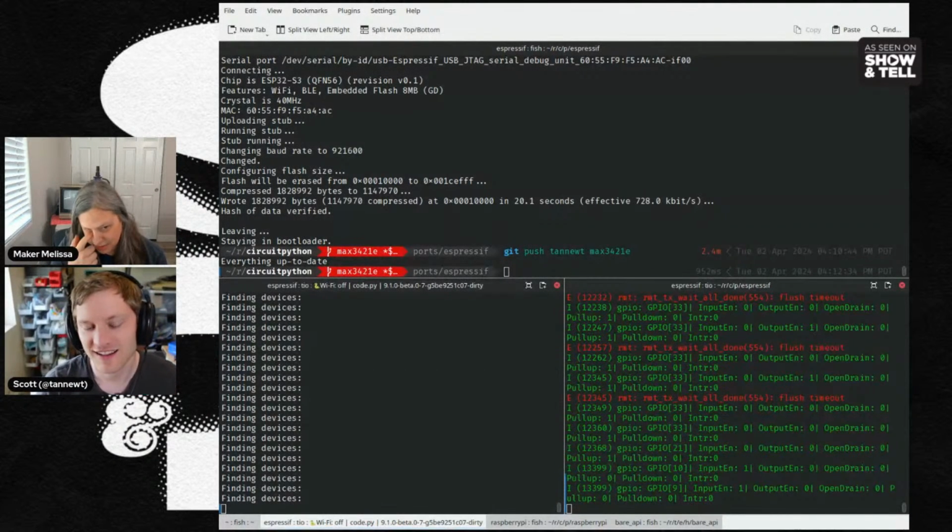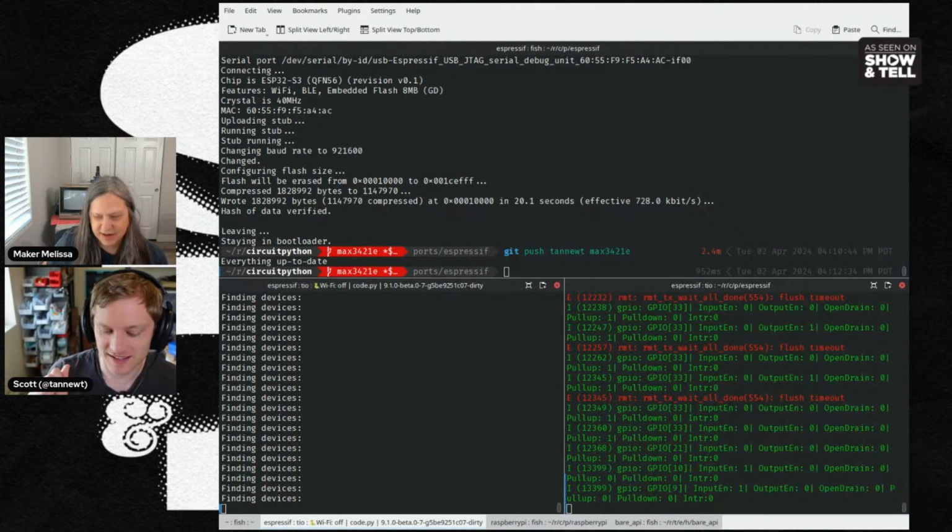Today I think this is part 3 of USB host Featherwing stuff. I did figure out my issue from last week, and it was that I had debugging UART in and out set up, but I didn't have the input connected to anything. So it was generating all that junk characters that caused my demo to fail last week.